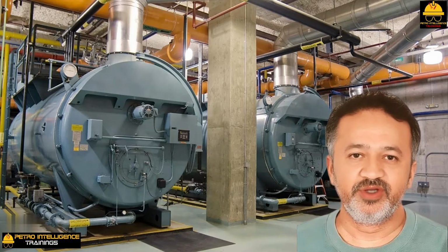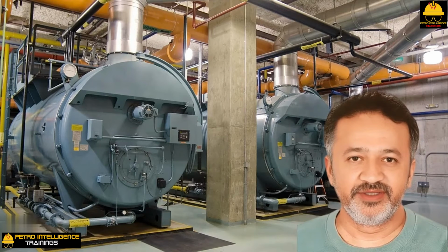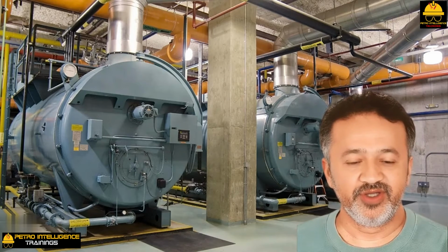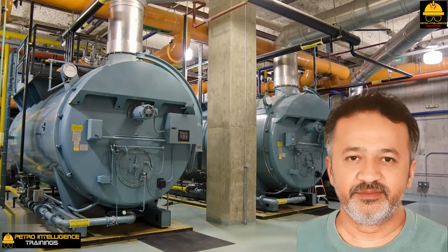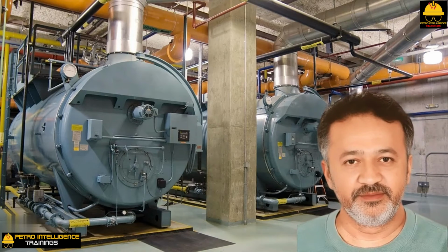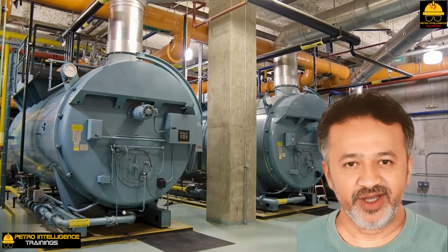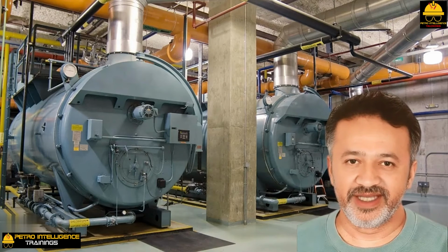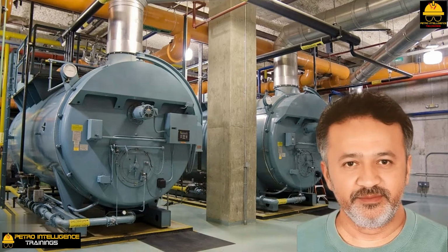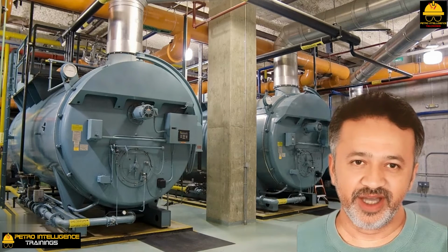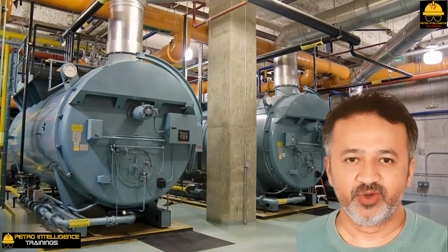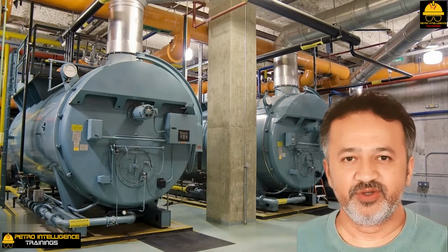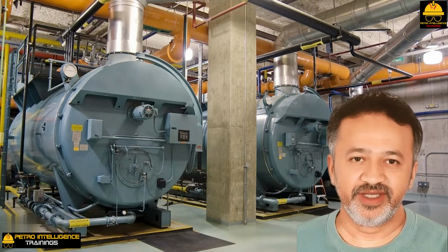Superheating steam for reboilers and steam heaters is mostly a waste, as it's a standard industry practice to inject condensate into the steam to bring the steam back to its saturation temperature. Superheated steam does not transfer heat as well as saturated steam. Hence, the de-superheating stations. As there is typically another convective section, usually BFW preheat, above the steam superheat tubes, no net energy savings result from steam superheat.